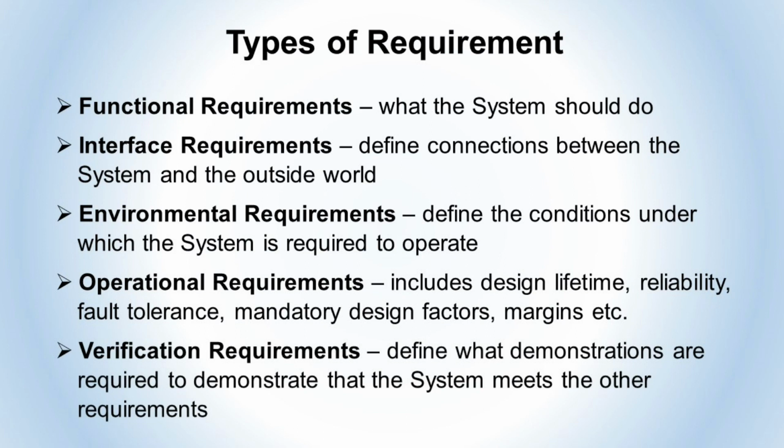Because some of the requirements are not always easy to establish by direct measurement, for example, will the spacecraft operate successfully on the surface of Mars, we need to agree what is a satisfactory demonstration that the system can perform what was called for. These can include calibrated analyses, where we do a limited number of tests, but then use computer simulation to confirm that the system will work over a complete range. We even sometimes verify by heritage.